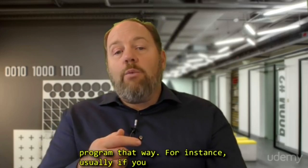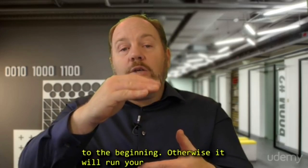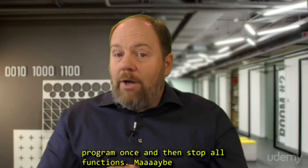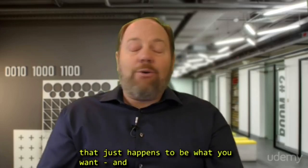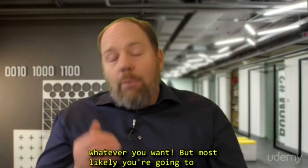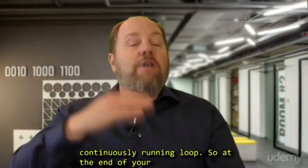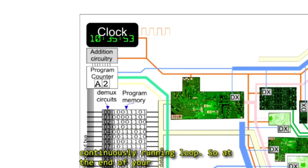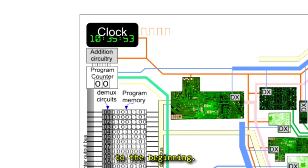For instance, usually if you reach the end of your program, you'll send it back to the beginning. Otherwise, it will run your program once and then stop all functions. Now, maybe that just happens to be what you want, and certainly you can. It's your program. You can do whatever you want. But most likely, you're going to want to run your program over and over again in a continuously running loop. So at the end of your program, you send a 00 hex to your program counter, and voila, you have just sent your program back to the beginning.